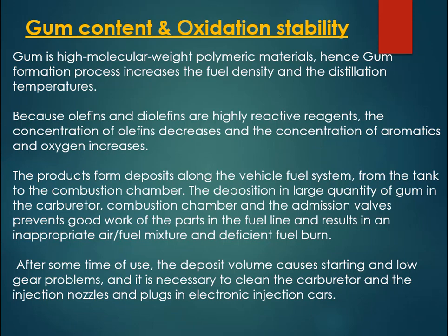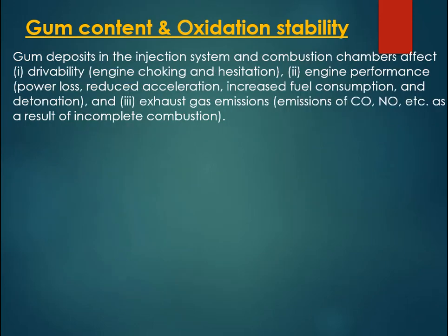Ultimately, if deposition increases to a very high volume, it may cause a starting problem, low gear problem, and ultimately it will necessitate cleaning of carburetors. And even in an electronic injection car, it may plug the electronic injector. So the problem associated with gum content may be understood from this slide. Okay, so I am going to summarize here.